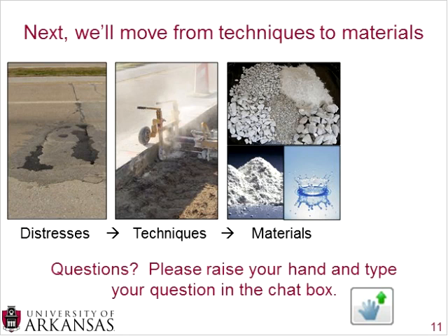I think that rubbleizing concrete is appropriate for 2 reasons. One, the entire project is in pretty poor condition, so there's a lot of cracking, a lot of these distresses that we've been talking about, and the agency or the contractor feels that it's really not worth replacing all of that. So they may rubbleize it and then put either an ultra-thin PCC layer, or what's called white topping, or an asphalt concrete layer on top, as an overlay.